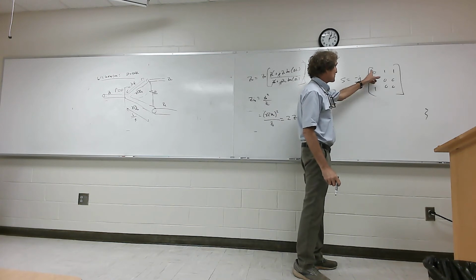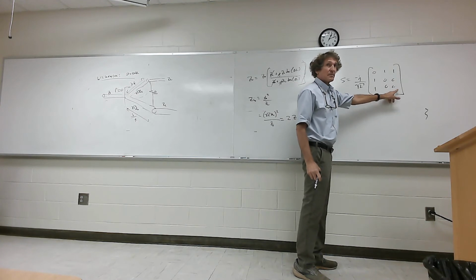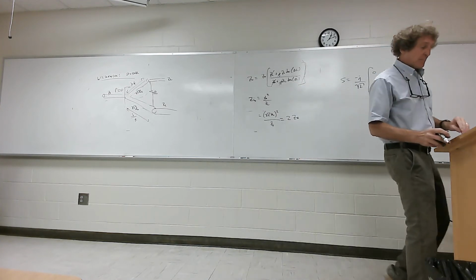The ideal thing is the reflection coefficients are all 0. That's the ideal, because you don't want any reflected energy. So it's not perfect, but it's a lot better than the actual resistor divider.